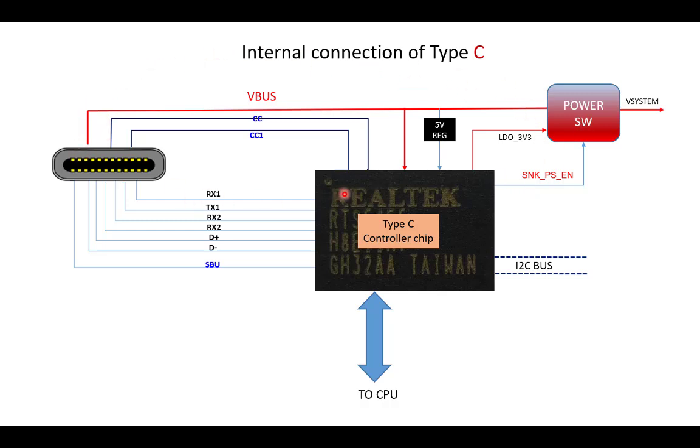In the power delivery system, you can see these three lines. One, the red line, is called the VBUS. VBUS stands for voltage. The power comes in and also goes out, so it is called bidirectional. And the power communication protocol is managed by this CC line. CC stands for configuration channel. So here there are two configuration channels, CC1 and CC2, but actually there is only one, because the cable is twisted, that is why there are two. Actually there is one CC line.